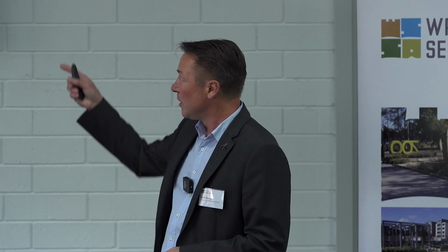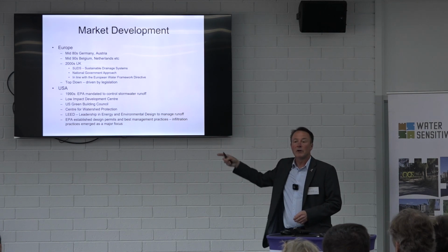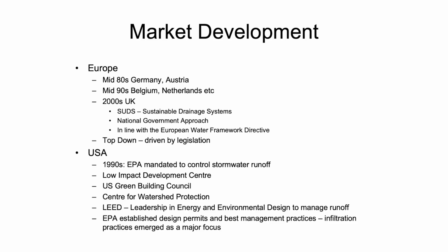And the USA is also driven by its EPA, who really pushed the stormwater agenda from a pollution control aspect in the 1990s. I've just listed some of the things that developers and designers have to consider when designing in the USA. So they've been very proactive. I don't actually think their designs are any better. In fact, they've got some faults with some of their designs in the States, which have flowed on to South African practice as well. For instance, they use very large base course materials compared to what we use, up to 50, 60 mil sometimes.